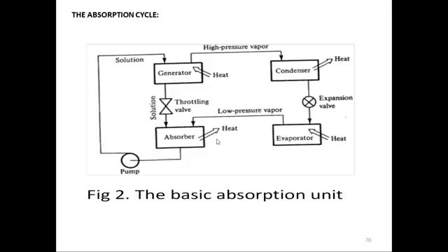It will be rejecting heat to the ambient, or you can have cold water circulating into the absorber. It will absorb some of the heat, so the process can continue. To perpetuate the absorption process, the absorber is cooled by water or air that ultimately rejects heat to the atmosphere. So to continue this, we need to eject the heat from the absorber.